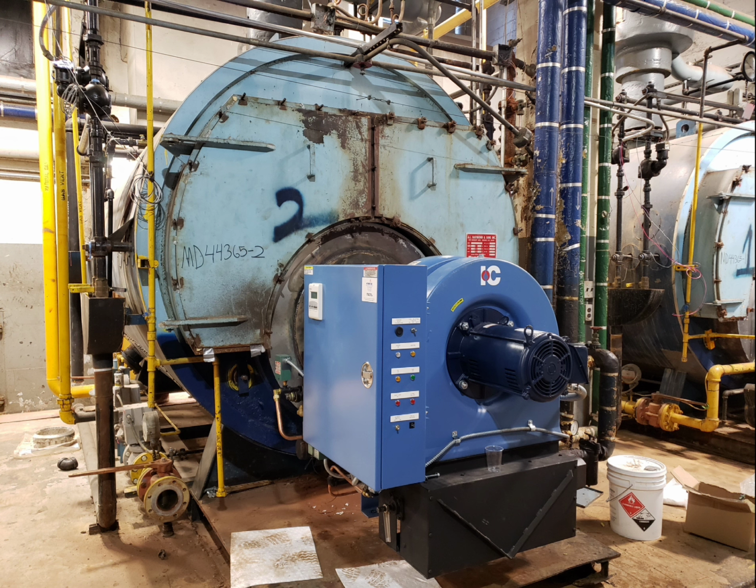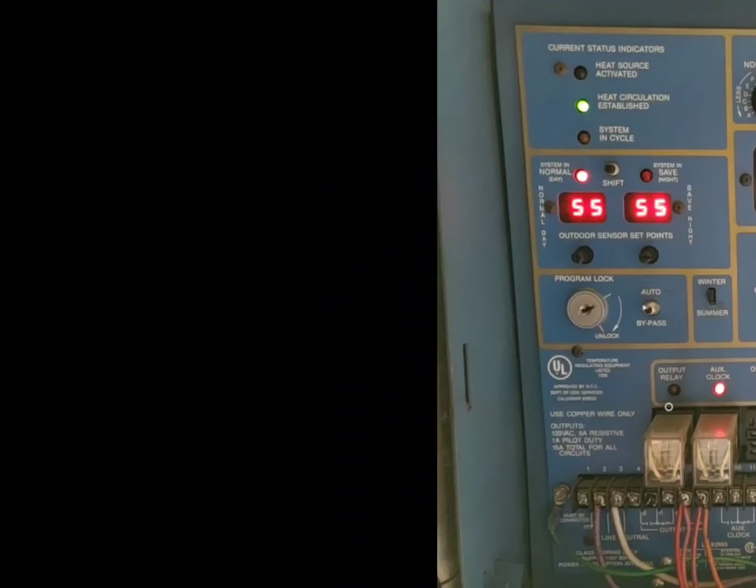Now, there's ways you can do that, and I'm not going to get into explanations in this particular, well, I might as well just go ahead and say it. You can do that through your L91, and that's through a modulator that pretty much will reduce the flame and hold it at low fire, and therefore you can run it at 2 psi without having to actually cut out the flame. And that's the way I did it when I was a superintendent for a number of years.